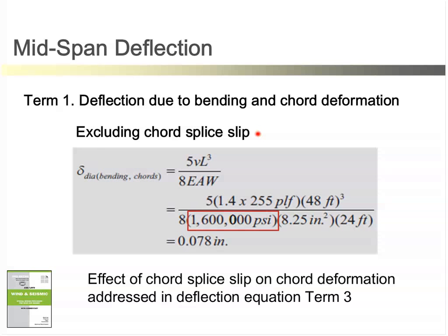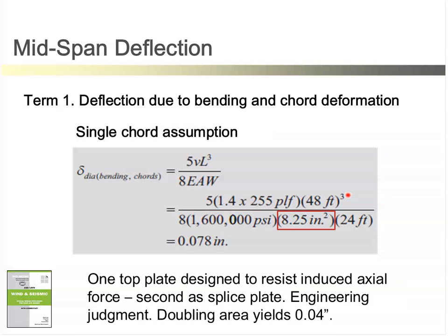And again, the assumption we're making is that we're using one top plate to resist that induced axial force. The second is a splice plate. That's engineering judgment.